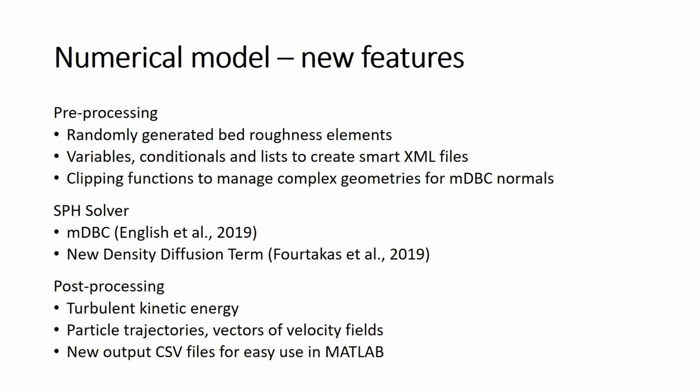Numerical model, new features. This research used the latest improvements included in DualSPHysics 5, released in July 2020, such as the modified dynamic boundary conditions described by English et al. and the new density diffusion term described by Fourtakas et al.